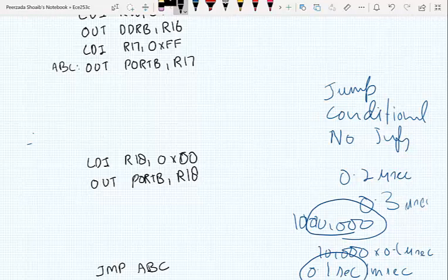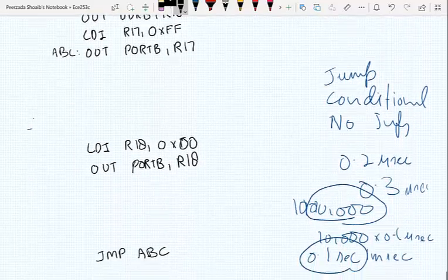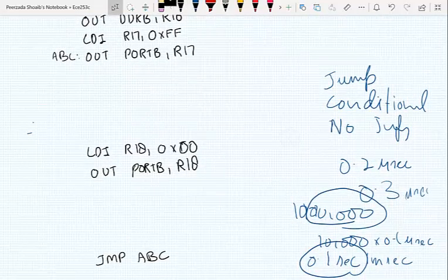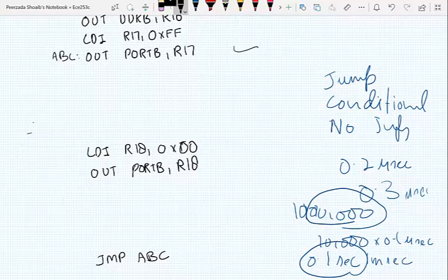First, I need to use a general purpose register as counter. I have used R17, R18, R16. Maybe I use R19 here. So what I will do after turning the LED on, I will actually execute a statement which doesn't do any job, no operation, maybe 100 times or maybe more. Since the limit for a simple loop is 255, we can execute it a maximum of 255 times. If we need large time delays, we use nested loops. Let's begin with using a simple loop.